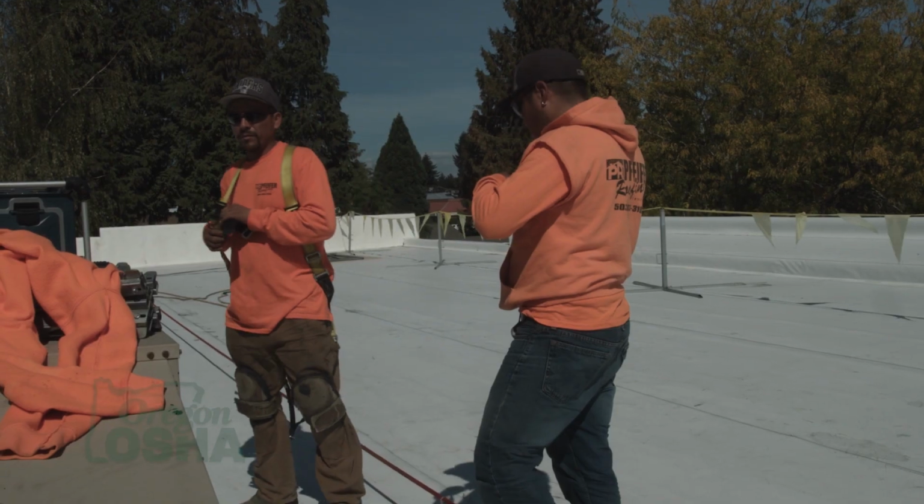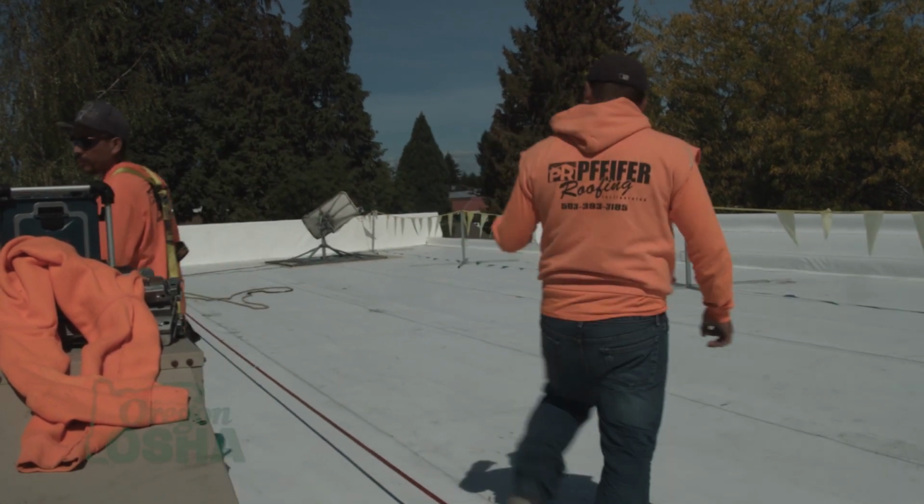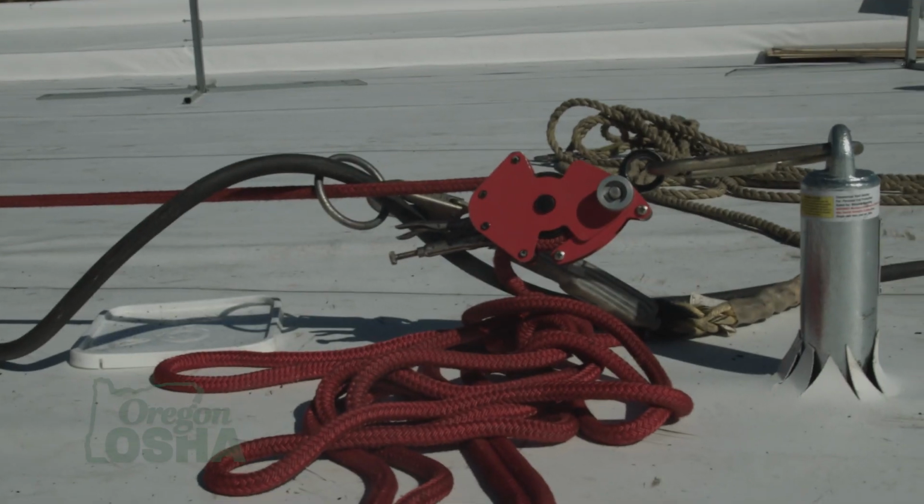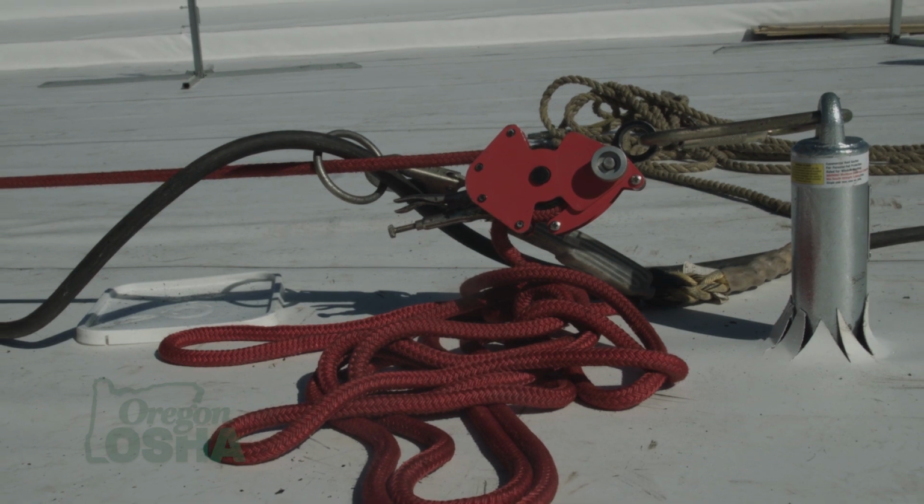We'll break it again into commercial versus residential. In commercial roofing, we see fall protection systems being used quite a bit, whether it's guardrail systems that go around the outside of the structure so that we're protecting everybody on the inside without having to put up active fall arrest equipment. We also see roofers more and more often working with building owners to put in permanent anchor points and maybe permanently installed horizontal lifelines, so that it protects not only the workers while they're doing the roofing, but we have fall protection for maintenance or other activities that would be happening once the roofing is done.